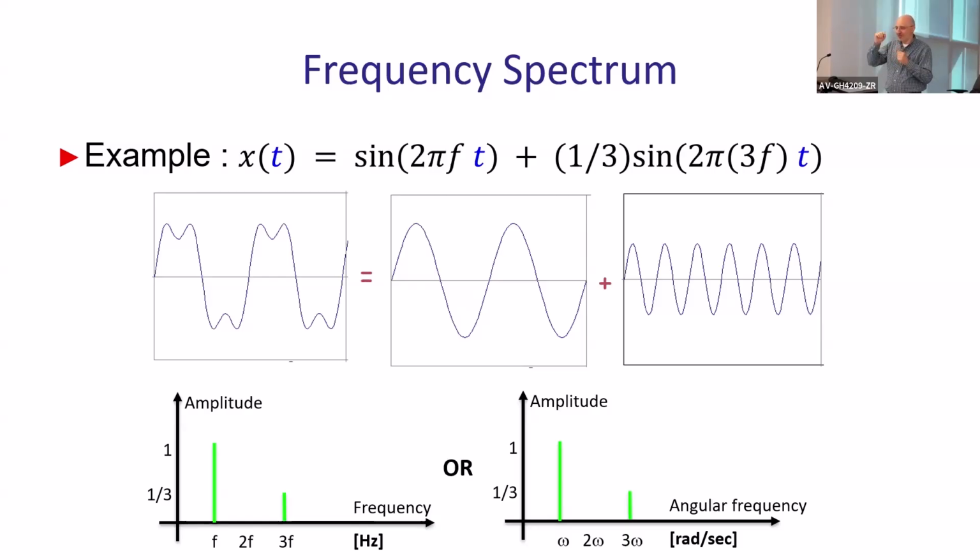Because you'll have a sine, a smaller sine, a smaller sine, and an infinite number of them to add up to the actual rectangular wave. Because as you can see, sine waves do not have corners. So you need to add more and more higher frequencies to mimic those tiny, very fast transients at the boundaries of the rectangular wave, when it switches to the step, right? So to model that kind of very strong slope, you need almost infinite frequency here, right? Because this frequency is kind of infinite.